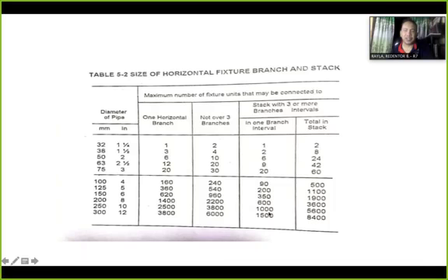This is now the number of fixture units. But the total in the stack, so nasa loob ng stack, di ba? Can you imagine a 100-story building with one single stack? How many branches? 100 branches, no? For example, 100 branches. And the total fixture units of the branches is more than 8,400.